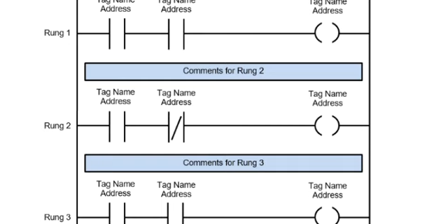Continuing with the same example, here are a few introductory terms related to ladder logic. As shown in the diagram, you can see there are vertical lines and horizontal lines. The vertical lines are called rails. There are two rails, one for the positive side and one for the negative side. The horizontal lines are called rungs, where we place our input as well as output devices.